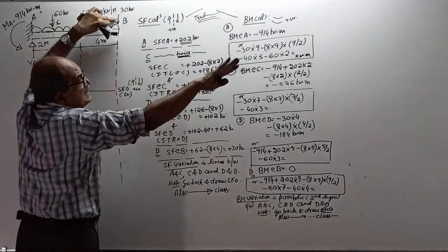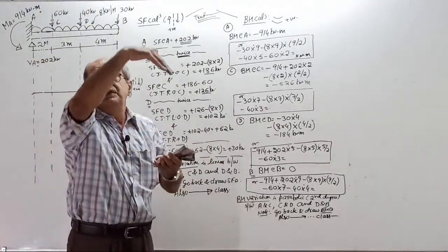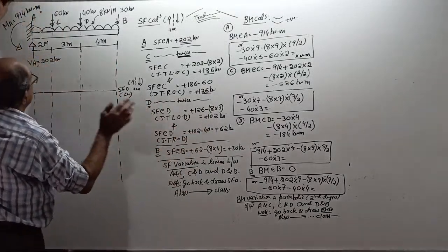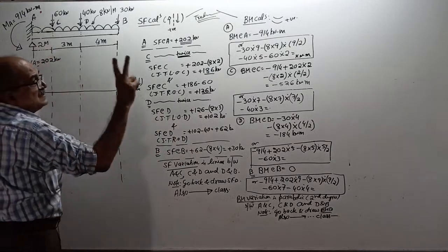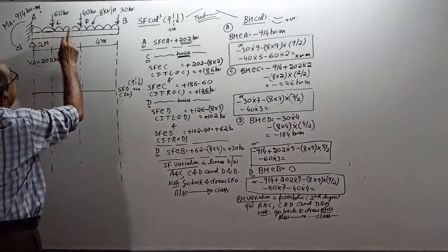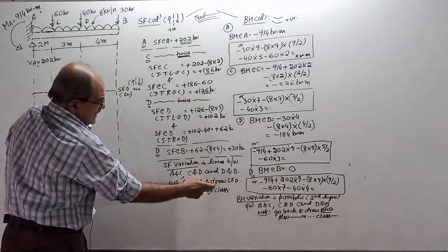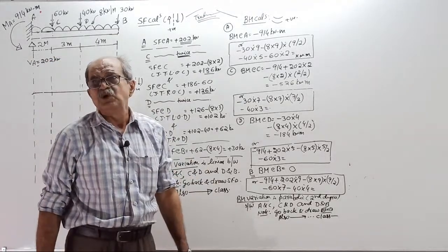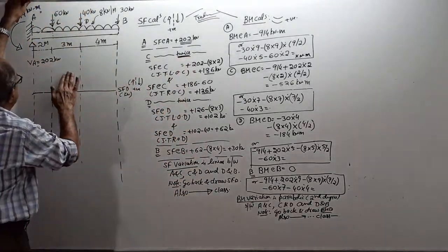Check the answer. If you look from the right side, downward 30. Shear force, right down is positive. Correct. 30. Then the usual statement. Shear force variation between A and C, linear. Between C and D, linear. Between D and B, linear. Write the statement here. Then go back and draw the shear force diagram. How? By observing these values, draw the shear force diagram.